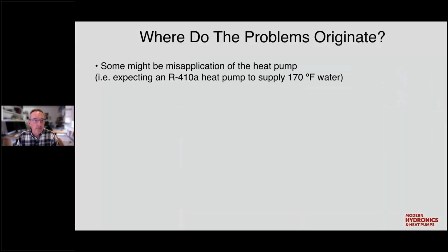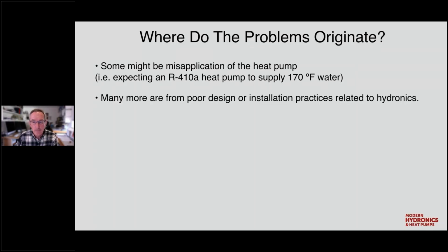So where do these problems originate? Well, some of them are just misapplication. I'm sure most of you that are watching this today know that an R410A heat pump really can't produce 170-degree water, but there are people in the industry that don't realize this. So we again need to look at what the refrigerant is, what the machine is rated to produce, and how its thermal performance varies with water temperature.